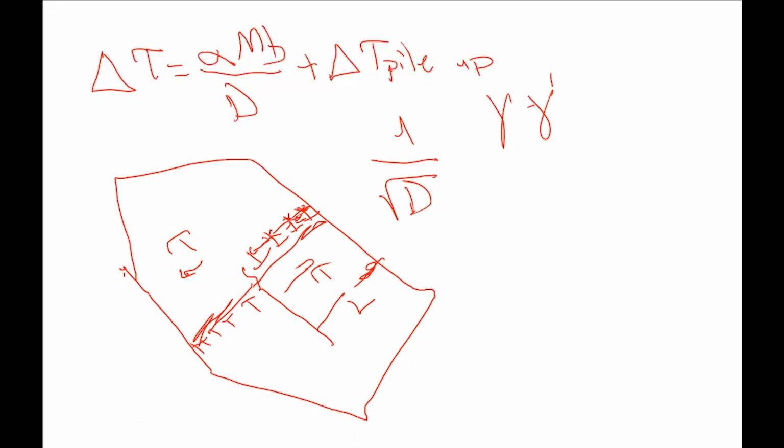And the number of dislocations in the pileup can be calculated as n equals k times tau times L divided by G times b. So this k is 1 for screw dislocation, and for edge dislocation, it is 1 minus Poisson's ratio, times pi times shear stress times L, where the maximum L is d, right?